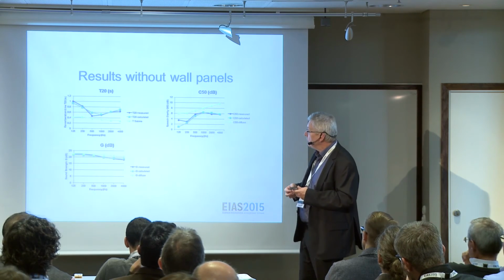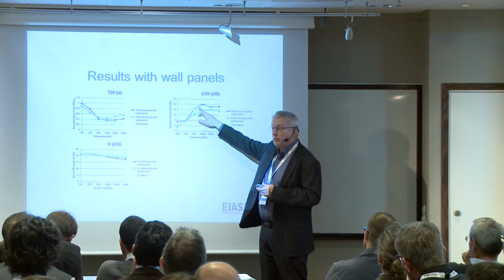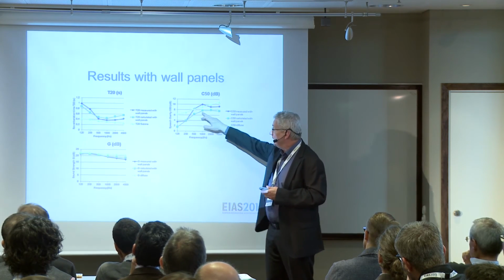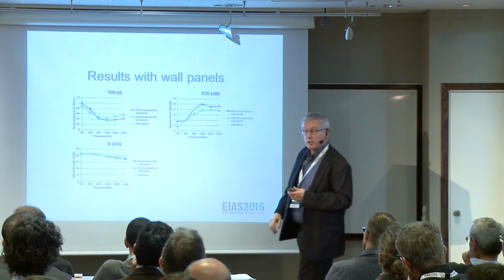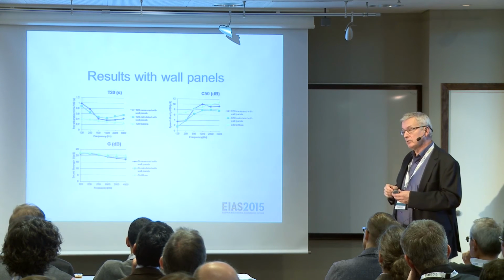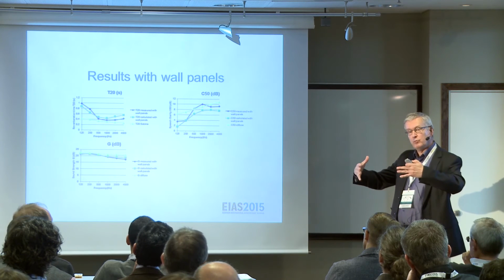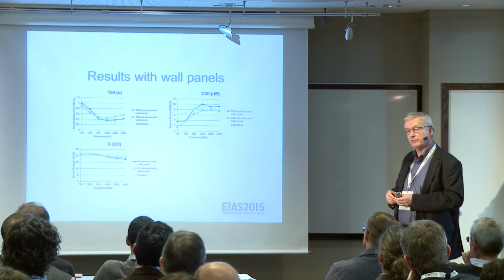And the effect, if I do that, will be that we will get an improvement of the absorption coefficient here. The strength and the reverberation time will be a little bit lower. But that's quite interesting because we can see those effects in these types of calculations, because the wall panels act more on the grazing field than on the non-grazing.